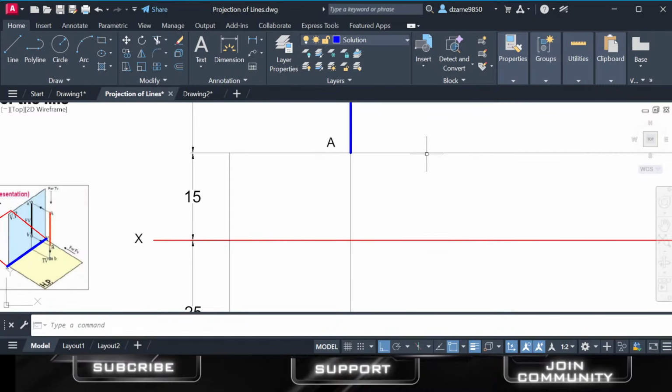But for you to draw it, you will not be able to get that point. So first of all, you have to draw a vertical line to give you the length, as you can measure using your straight edge. So in this case, I just want to draw that one. And as you can see, it's 15 millimeters. But in AutoCAD, again, you can hover over there and type 15 millimeters. You select 15 millimeters and press enter. It will snap to that point. Already it has locked 15 millimeters.